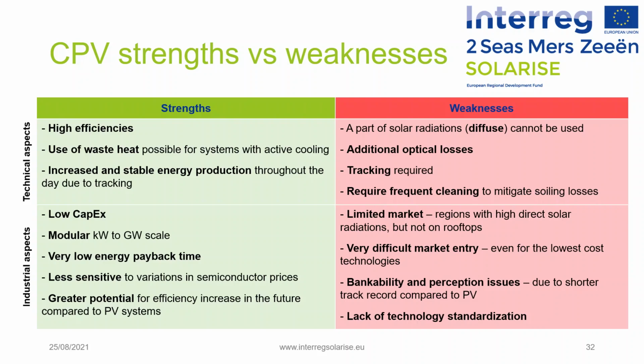Nevertheless, concentration implies harnessing only the direct solar radiation part, even if there is some research about harnessing also the diffuse radiation part, and the addition of optics implies additional optical losses, a need for sufficient and reliable tracking, and frequent cleaning.